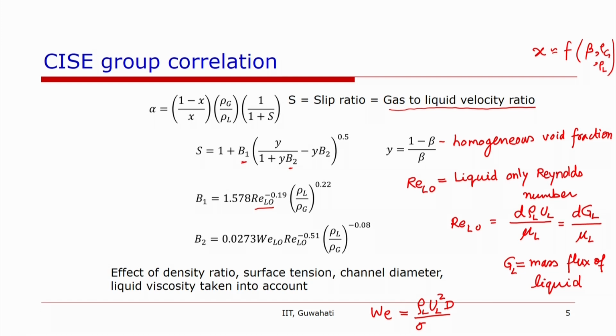If we look at this correlation, care has been taken to take into account the density ratio. We can see the density ratio in a number of places. It takes into account the viscosity of liquid using Reynolds number.